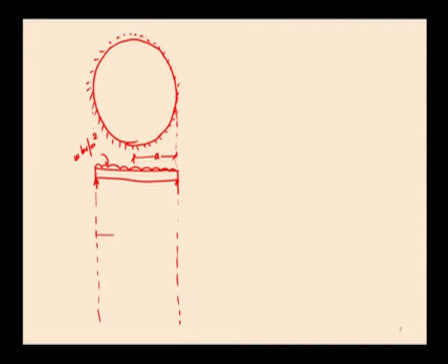This is the radial bending moment diagram and the circumferential bending moment diagram. It is denoted by M theta diagram, that is the circumferential moment diagram. The circumferential moment at the center is 3 by 16 W A square, and the circumferential moment at the edge is 2 by 16 W A square. This is the circumferential moment diagram for a simply supported slab.